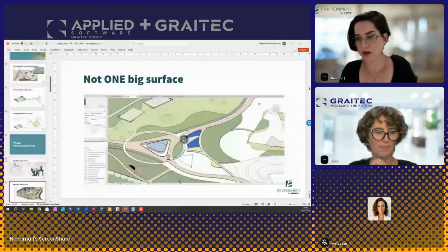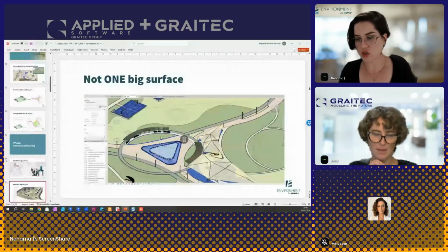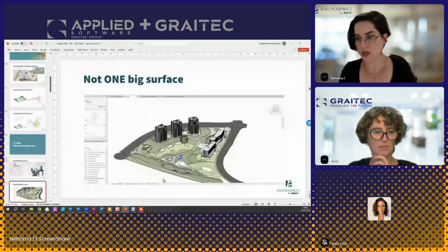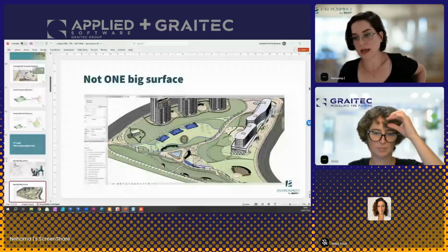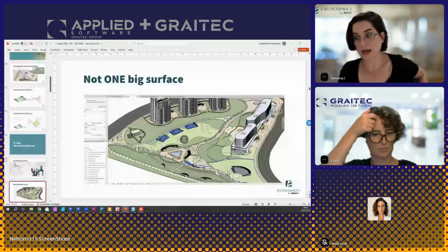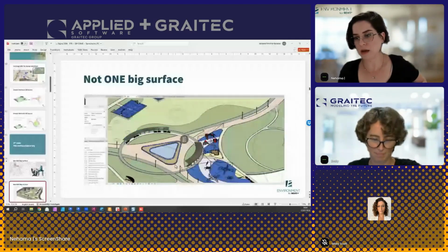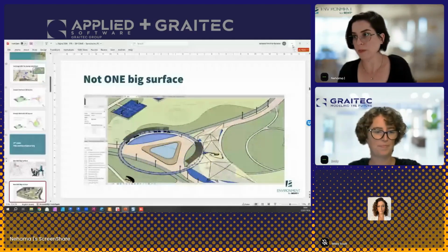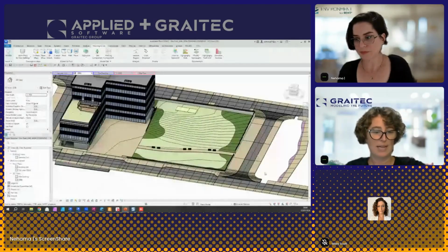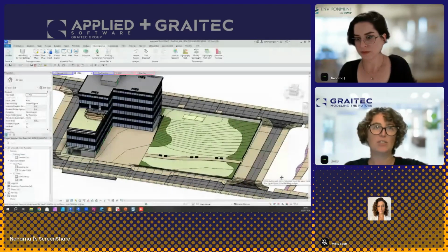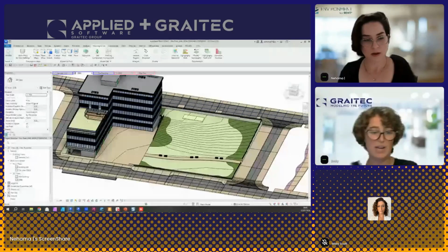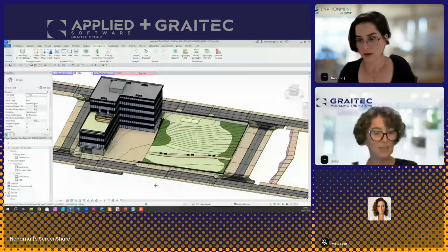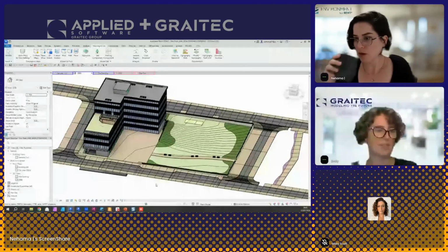So I would definitely go with your answer. Just break it apart and make sure that you're working with each part the way it should be. And then you can get to a very, very accurate result. Again, in my opinion, I got better results than CAD because I could see it in 3D and design it in 3D and understand what I'm doing. Yeah, I tried to do a really large site in chunks, but the chunks were still too large, and I spent a lot of time waiting for Revit to just think about all those points. So for detailed terrain, smaller segments are a must.